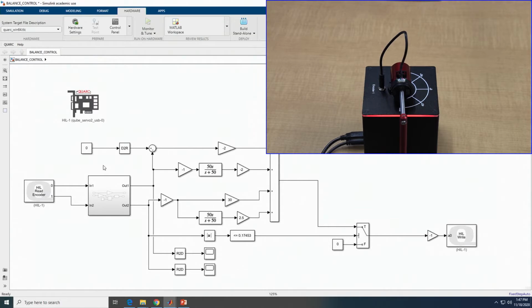So this is the block diagram for the PD controller, designed to keep the rotary pendulum at an upright position and also to keep the arm angle theta at 0. We basically have the same PD controller as the one that we had in lab number 4, but here we have 2 additional channels because we're controlling both theta and alpha. So there is a new block here that we're using. It's the switch. The switch enforces the small angle assumption that we had. So the switch outputs the control signal when the alpha angle is smaller than 10 degrees and returns 0 otherwise.